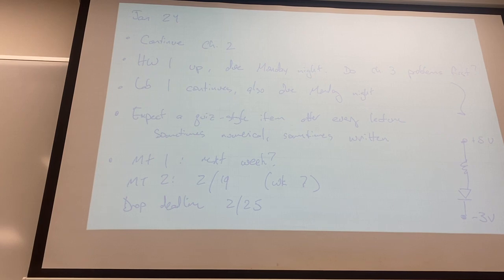The book has many different methods of solving diode circuits and sort of increasing level of detail. Their so-called ideal model is to assume the diode turns into a short when it's on and is an open when it's off. That's even simpler than what we were talking about. Their constant voltage drop model is what we've been doing. Sometimes they call it constant voltage drop, and sometimes the problems abbreviate it as CVD. That's substituting a voltage source in when the diode is on.